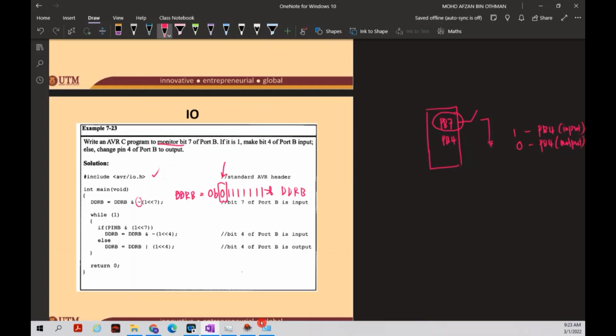Alright, so next, after you initialize your port B7 as an input, I forgot again here. Make sure that you enable your port B. Bit 7 enable the pull-up resistor. You can simply put 0B10000000. Or you can, if you don't want to change any value inside of this port B, from bit 0 to bit 6.